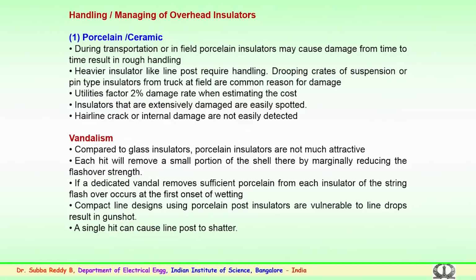Insulators that are extensively damaged could be spotted, but sometimes it may be difficult. Hairline cracks, as mentioned, or internal damage are not normally easily detected, and this could bring down the system. So, careful handling of these is very important.